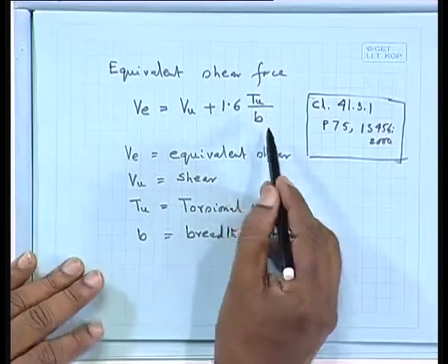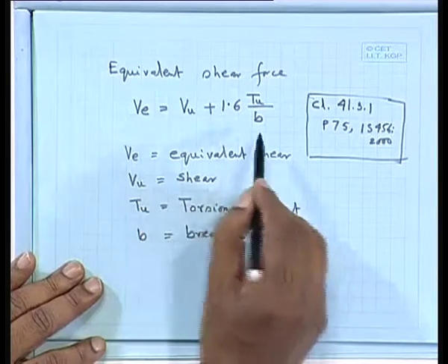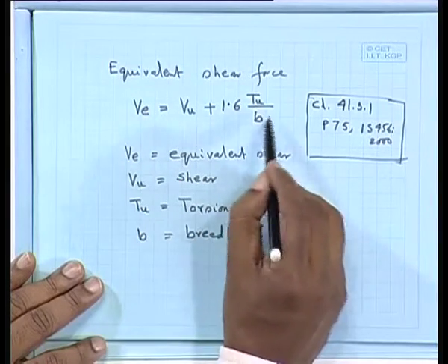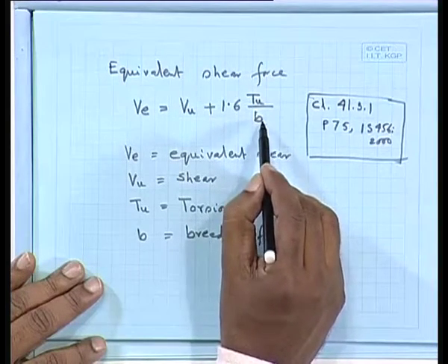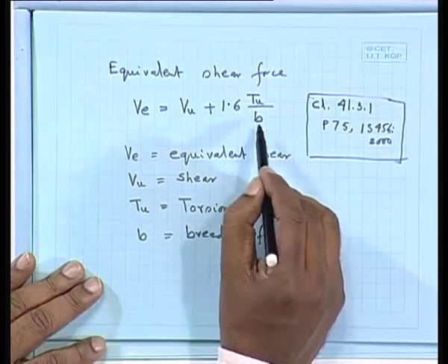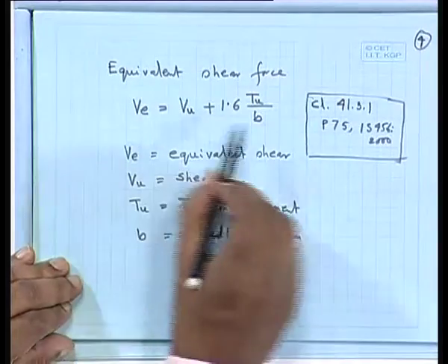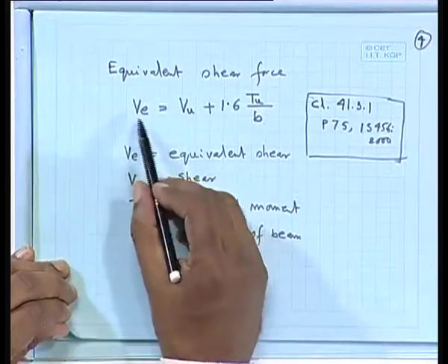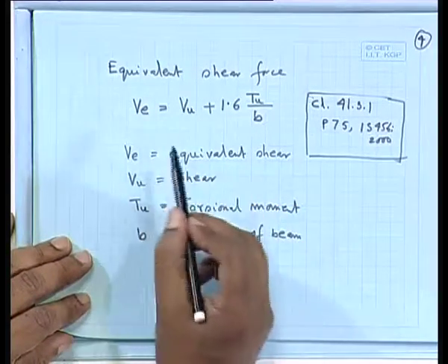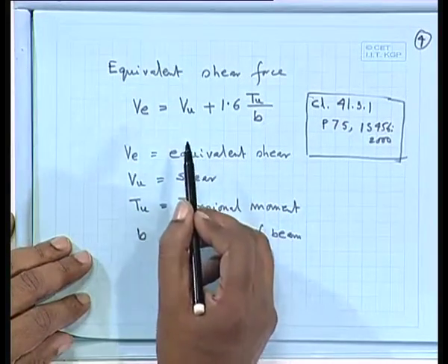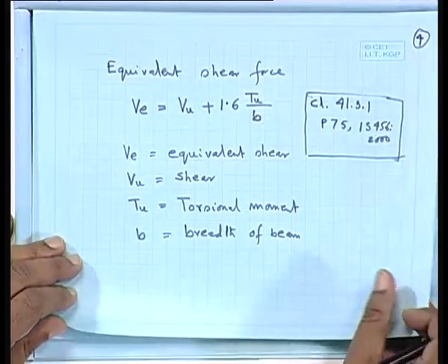So, in unusual cases where the shear force is quite high, we can reduce it by taking proper B, though it is a linear parameter. There is no big thing; using this equation let us find out the corresponding equivalent shear force, and then we shall go as per the standard procedure of design of shear.